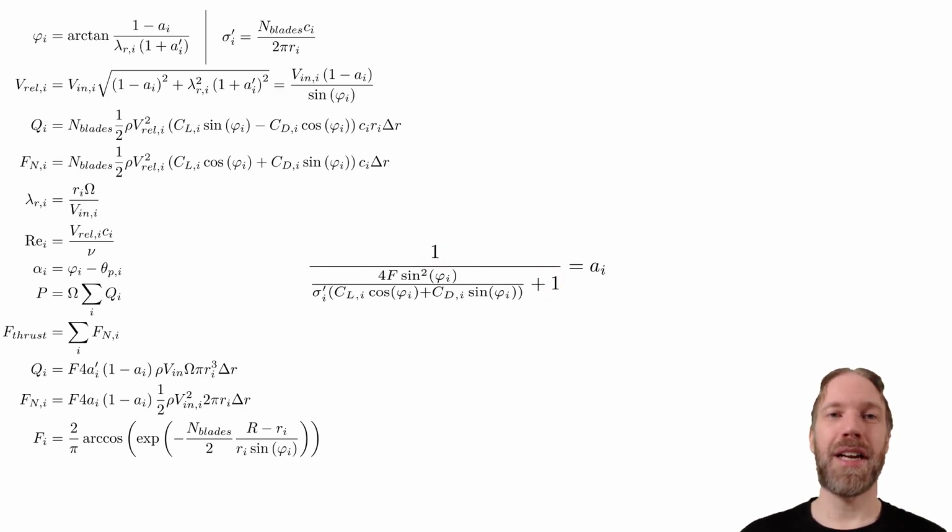This expression allows us to calculate the actual induction factor if we know the angle of relative wind and lift and drag forces. A common approximation here is to neglect the drag in the calculation of A. This is a good approximation unless we have stalled the blade. We will keep the full expression for now though.